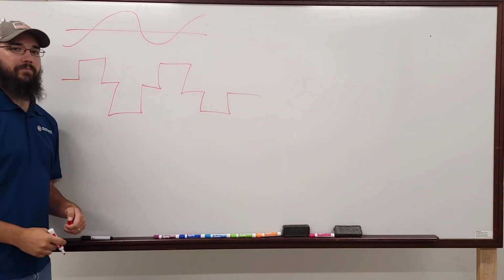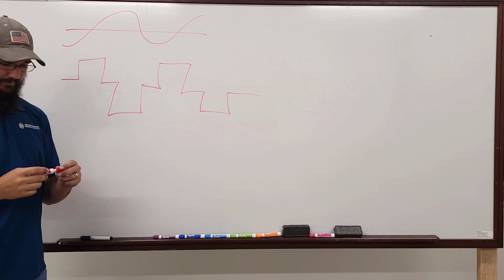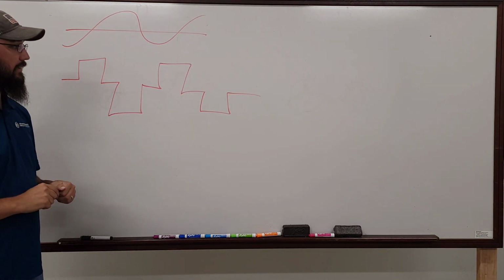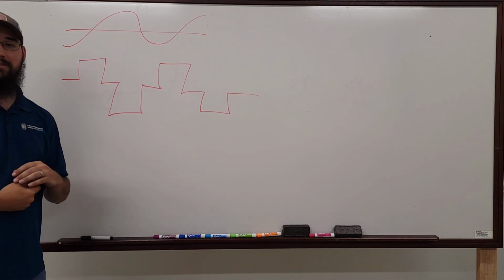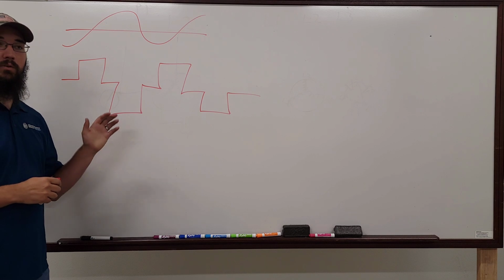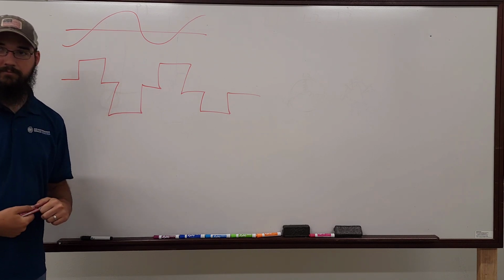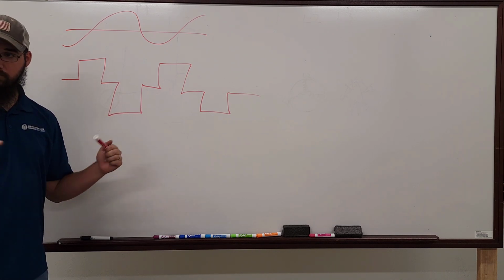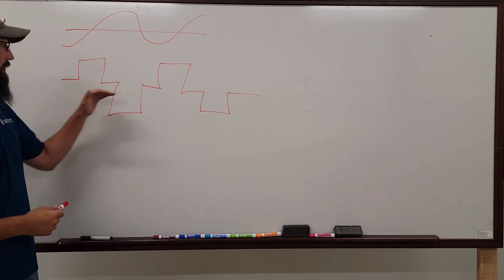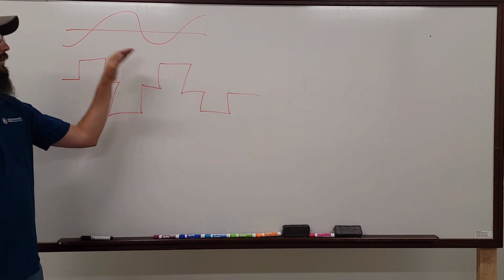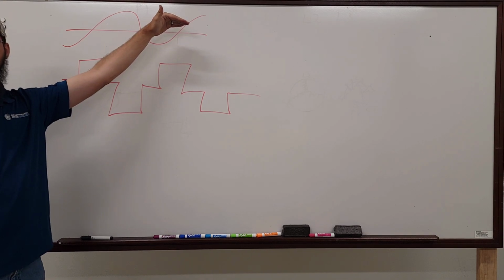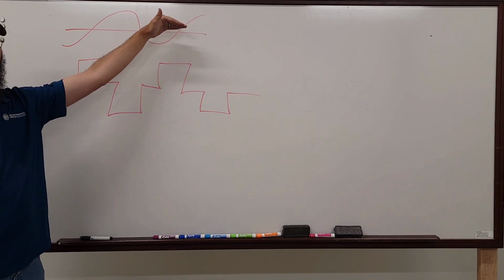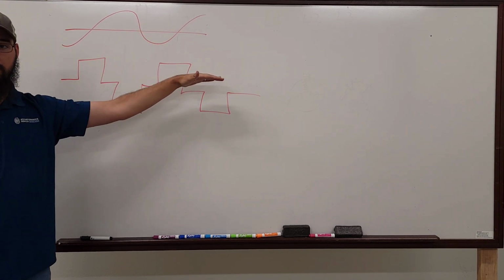And this is a VFD sine wave. It's a PWM, a pulse width modulated sine. Okay? Totally different concept. And yes, this is coming out of a VFD. It goes into the VFD looking like this, on an oscilloscope, and comes out of the VFD looking like this.